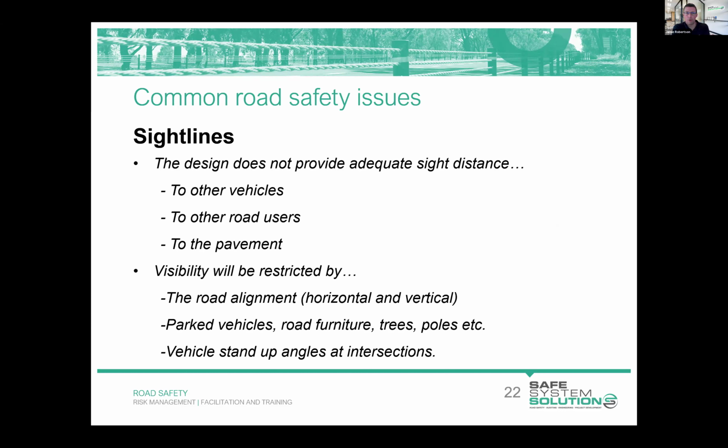So a design might not provide enough sight distance. When doing an audit, I encourage you all to get out there on site. If pedestrian crossings are proposed, walk across the road at those locations. Think about whether you would feel safe doing so, whether you have adequate sight distance. If you don't think you do, then certainly consult your standards to back up your finding.